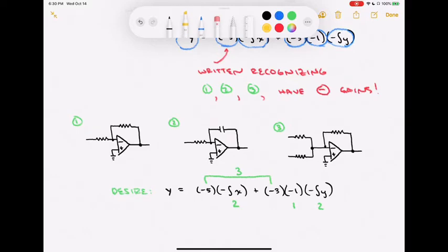So the first one is the scale factor. This guy is my integrator, and this guy here is my summer. It's going to sum up 2 pieces. We had an expression for y, and we saw that y was minus integral x, then carried through with a minus 5, getting summed to a minus integral y made positive, and then summed in with a gain of 3. I've labeled each piece that's in a parenthesis with the part that I need to do it. There are 2 pieces in there that involve integrations, and I've labeled both of those. I had minus integral x, that's going to have to go through an integrator-like circuit. I have minus integral y, that's going to have to go through an integrator circuit. I have something that is going to require an overall sign change, or a gain factor of minus 1.